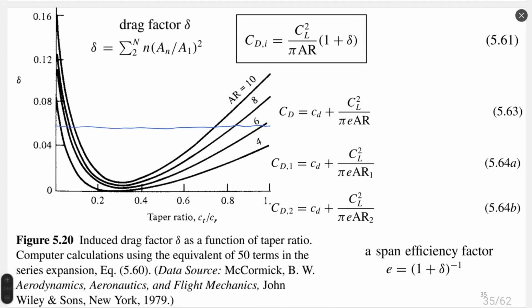Near 5%. Taper ratio, I would like to remind you, is the ratio between the chord size at the tip of the wing and at the root of the wing. This taper ratio is always smaller than 1, and says for us how different these sizes are. This is the tip chord, okay? This is on the wing, right? The flow goes in this direction here.